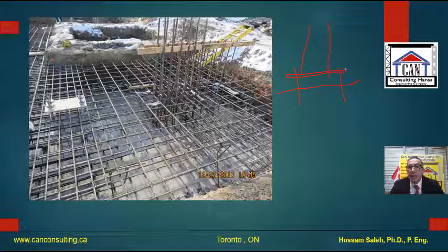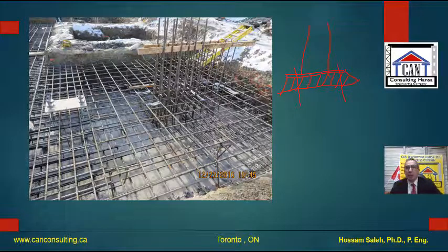And we said that here we'll get grout to make sure that you have full contact between the base plate and the concrete surface. So how can you construct or place the anchor rods? Here you have a schablon, or a template, and then you can put your anchor rods inside your formwork or your concrete member, and you need enough length from the top.